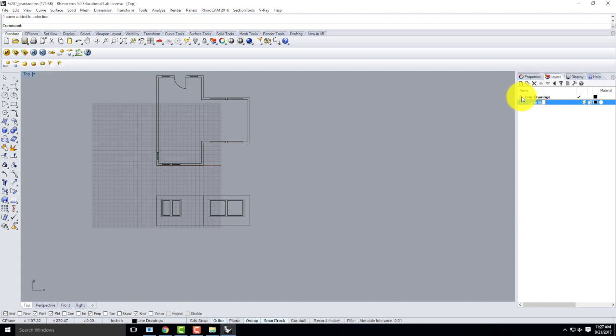And you see that now I have a plus sign and then a sublayer. We'll call this Plan. I'll go back to Line Drawings, create another sublayer, and we'll call this Elevation, or Front, or whatever works for you. Just because I call it plan or elevation doesn't mean you have to call it that. It's just for clarity, something that you need to understand. So I have Line Drawings, Plan, and Elevation.